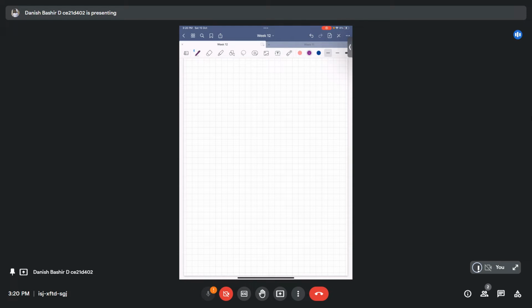And we also have moments per unit width. I already wrote them, let me write that again. Mx per unit width, because we are taking the strip per unit width. Okay, Mx will be wx lx square upon 8, same for My per unit width, wy ly square upon 8. Okay.